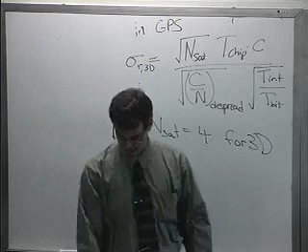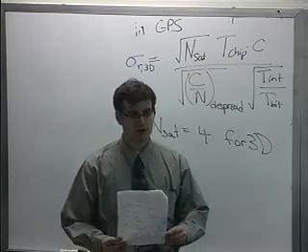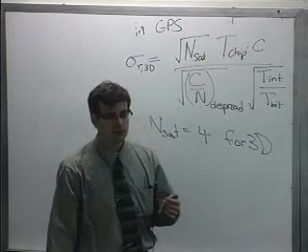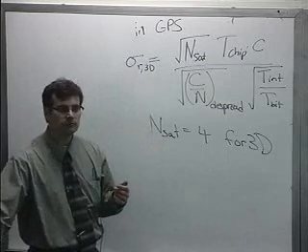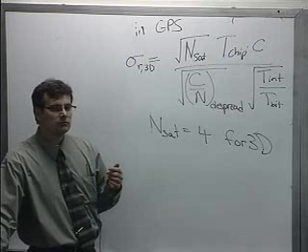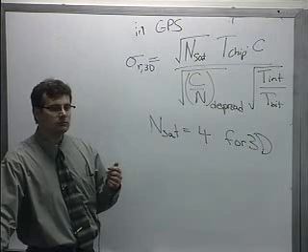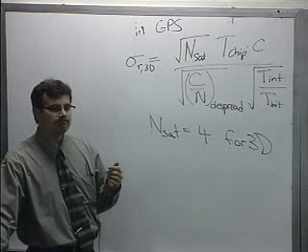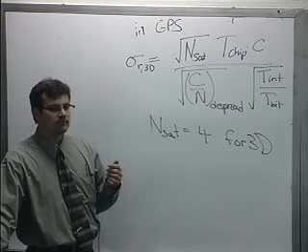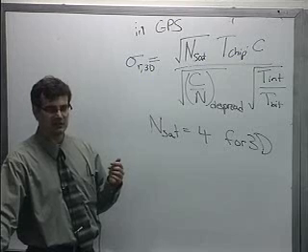What you were discussing with Rafi, the maximum resolution that we can have, depends on the sampling rate at which we are sampling our signal. It doesn't depend on any chip rate or anything. We are sampling 4 samples per chip, which means the resolution is restricted to the sampling rate. That's right. Sampling. No, not in super resolution techniques.